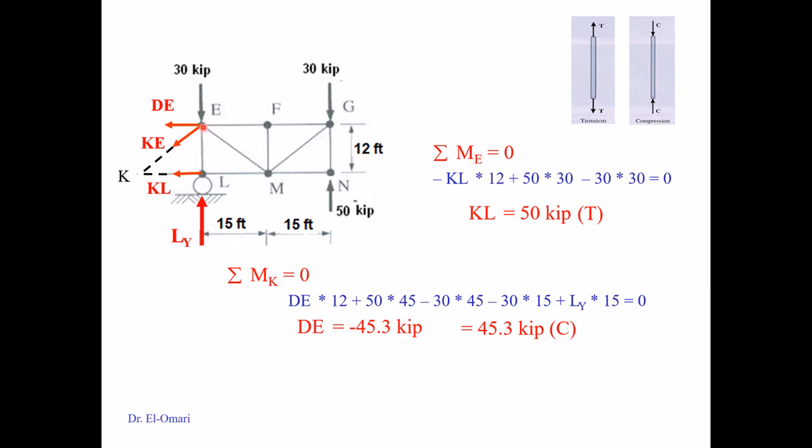Finally, I could use just forces in the y direction to get this remaining last one. To get the force in the y direction, I can now use the y component of that force Ke in the formula. Before doing that, I need to know the slope or the angle. Given is the 12 and the 15.